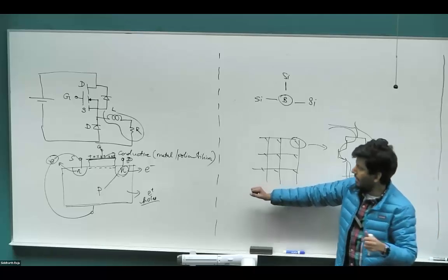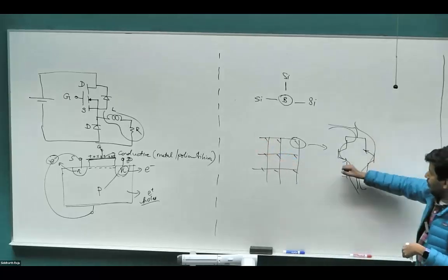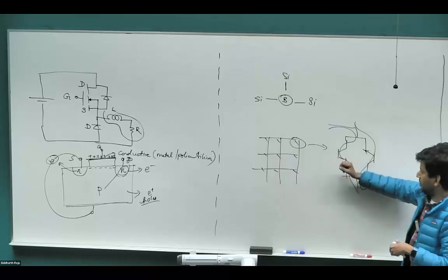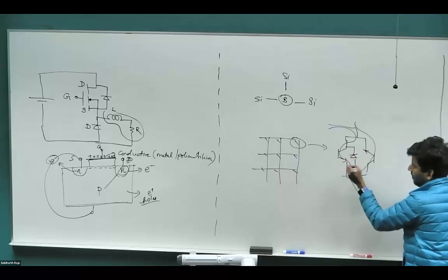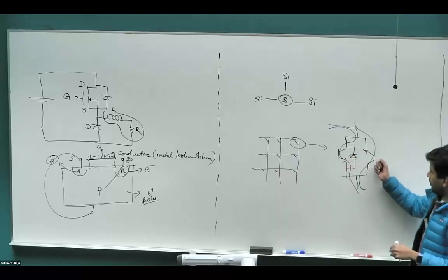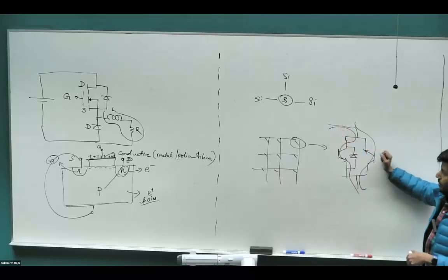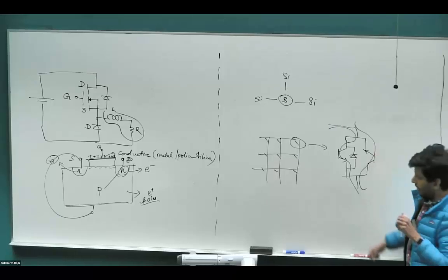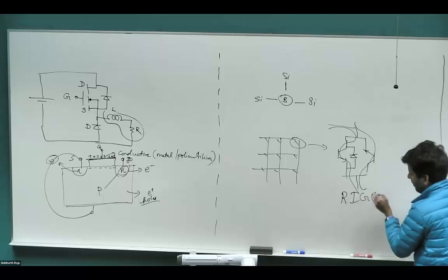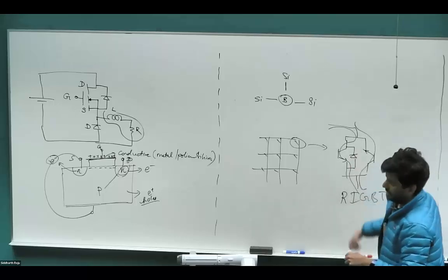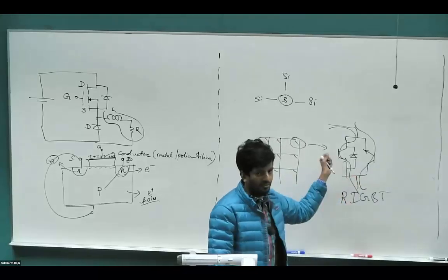That's called regeneration. And when you want to do that, you want the power to flow in the other direction as well. So you want to have control over the power on both directions. So you can use the switch to turn on this side or this side. But that would be defeated if you had a body diode here. Okay, so even whether you turn the switch or not, the current can flow through this body diode whenever it chooses to. So you don't have the degree of control there. So those are called RIGBT or RGIGBT. Right? But basically without the body diode. So they do manufacture those, but it's very limited though. There are only few applications that would require those.